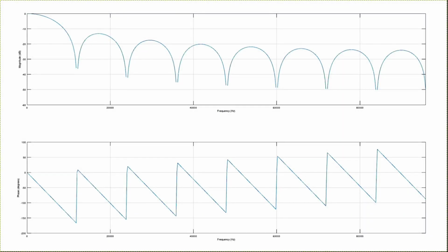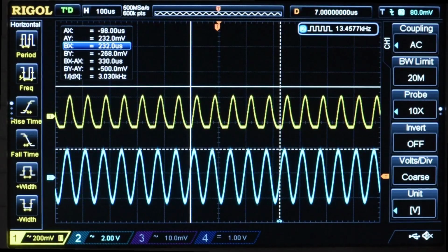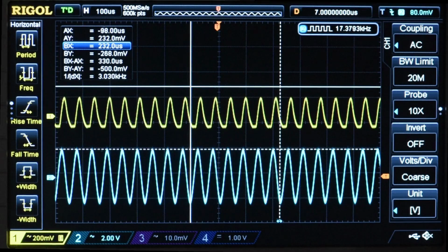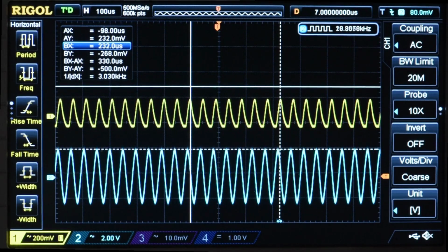I'm not even sure if this is the correct frequency response for a 16 sample averaging filter, sampling at 192 kHz. I couldn't seem to find much information on just an averaging filter. But if it is, only getting a 12 or 13 decibel reduction at say 18 kHz, that's not really going to cut it.